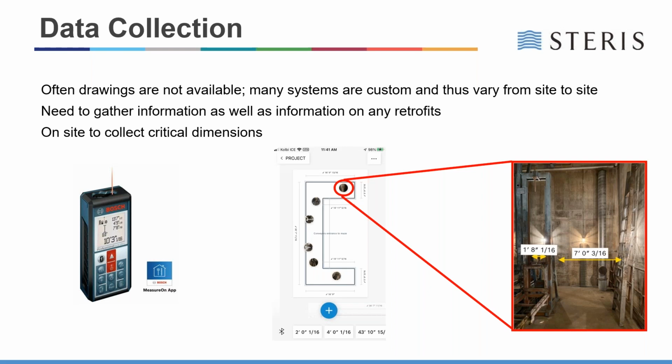In addition to this, we also have the common tape measures and calipers and squares and the common tools that you would expect to be able to measure the site details. And all those measurements are recorded within the software that we use to be able to collect this data. So with the tools described so far and the methods that we've covered, we've been able to outline a facility. And that's everything that goes into building that model. And what we'll see next is the accumulation of all of these measurements into a CAD model.